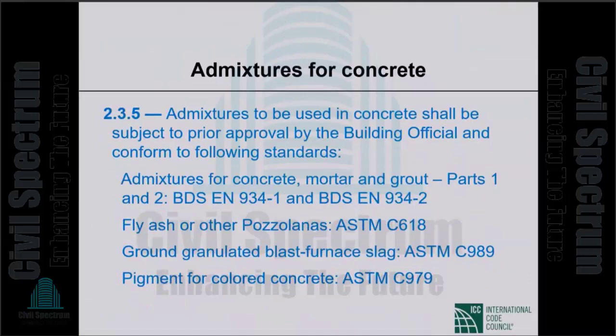Admixtures to be used in concrete shall be subject to prior approval. This ACI doesn't require this, but BNBC does. Admixtures to be used in concrete shall be subject to prior approval by the building official and conform to the following standards. So BDS EN 934-1 or BDS EN 934-2.